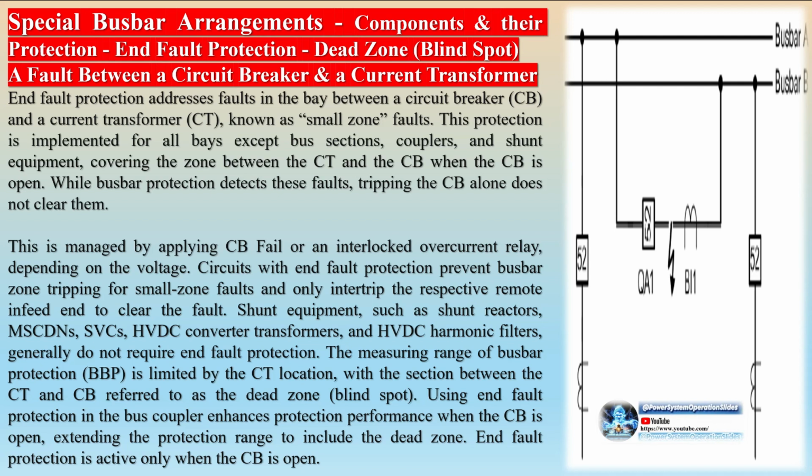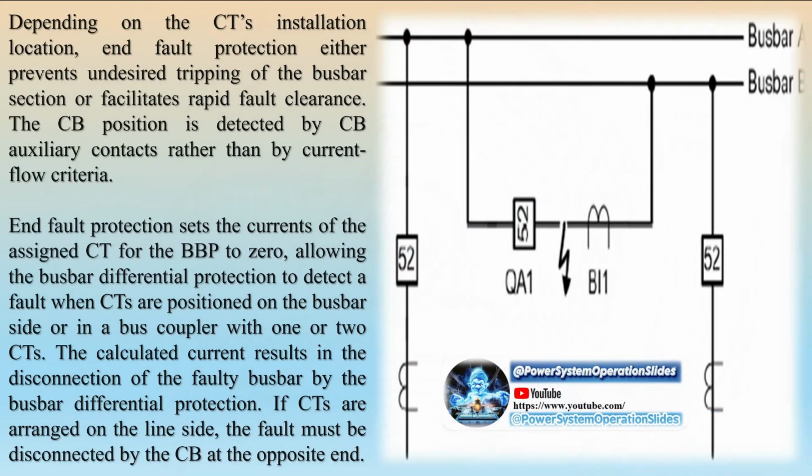Internal component failure supervision. This function oversees various internal components, including watchdogs, bay links for decentralized arrangements, and power supplies. When a faulty disconnector position or internal component failure is detected, the actions can include alarms, possibly delayed, or full or partial busbar protection blocking.